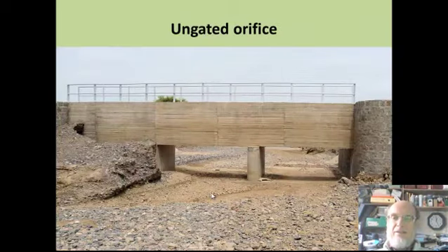This intake is an ungated orifice. In fact, the farmers will provide a gravel embankment in front of the intake if it is not its turn to take water. It will be done by the downstream farmers. When it is their turn, they block this intake further upstream. But the orifices, there's actually 3, will restrict the maximum flood flows that enter the canal.